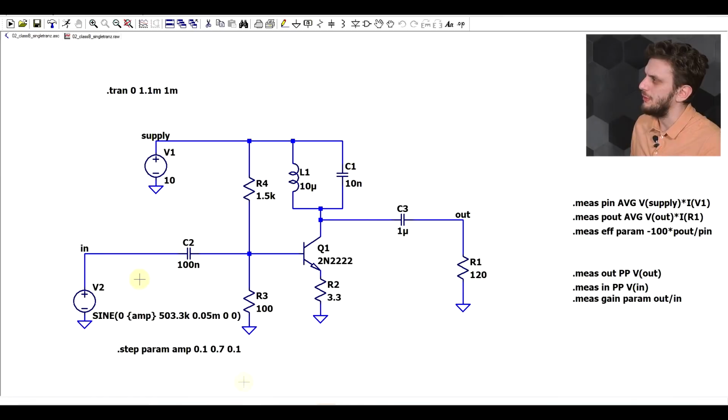Now, final thing to mention about this sort of setup is that since it uses an LC circuit, its bandwidth is limited. So first of all, this LC circuit needs to have a relatively high Q factor, and secondly, the amplifier will only work within a restricted range of bandwidth. So even though this works in Class B, this particular implementation is a narrow band circuit, with all of the limitations that it comes with.